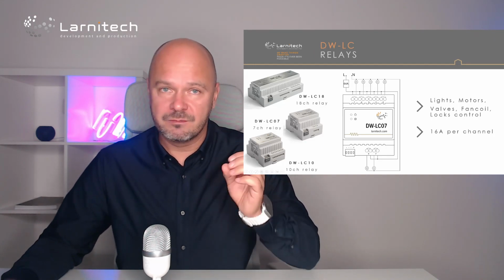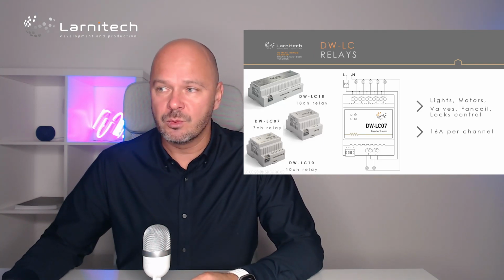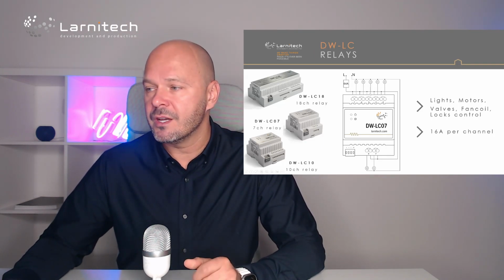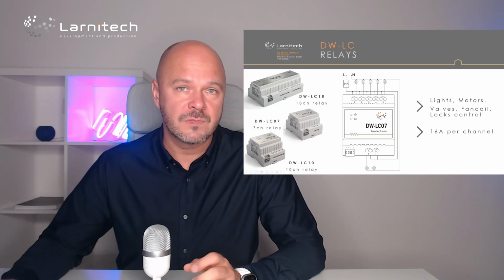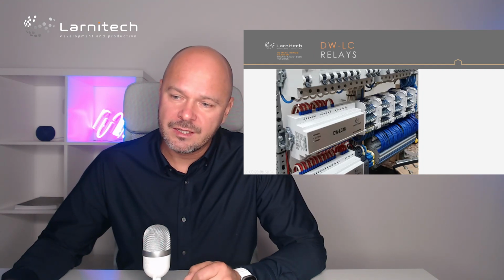So these are not just standard relays that open and close. These are very smart relays with different functions inside. And about the power, you can use up to 16 amps per channel. So they are 16 amps per channel. So this is the real world installation. This is how it looks in the DB. So you see the white one, it brings the phase, for example, and then another one, the red one, it gets the phase to the light which we control. So this is what it is.